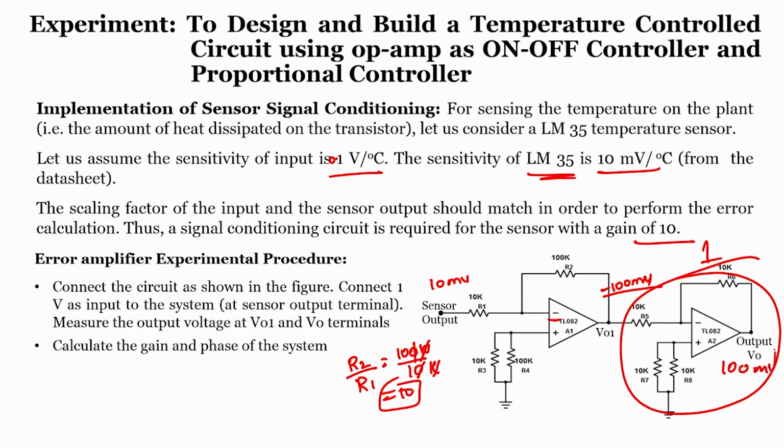So, the problem is solved, but is this the only way to do it? No, we can also choose a non-inverting amplifier with 20k and 2.2k resistors. When we calculate, the gain will be approximately 1 plus 9.08, which is 10.08, approximately 10. With a single op amp we can also do it, but I have chosen this way. It is not compulsory that you always go with the same one, the only thing is that it should provide us a gain of 10.